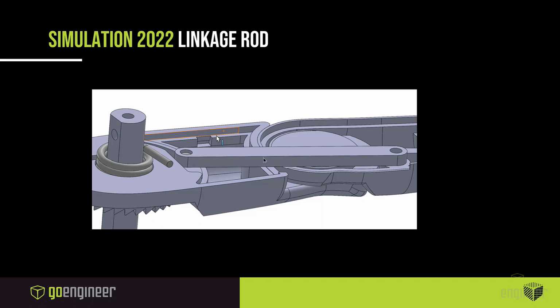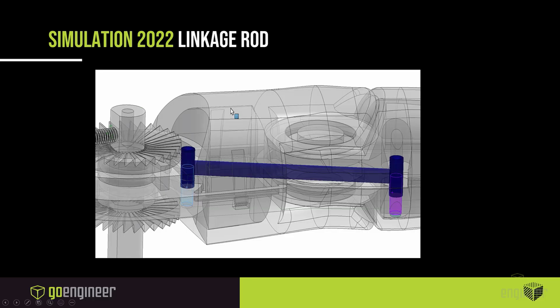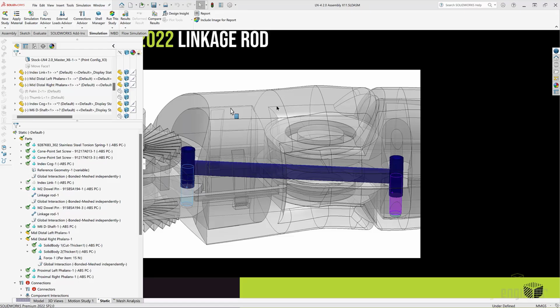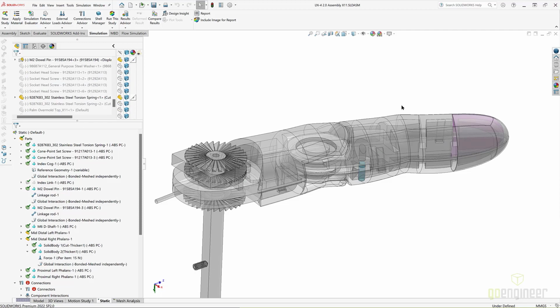And once that was done, SOLIDWORKS has to actually apply those loads to the model and then equate what's going on. So since we have a virtual connector instead, this cuts down the runtime because it can better calculate what's going on versus represent what is going on. And I'll show you the basic setup of what this looks like.